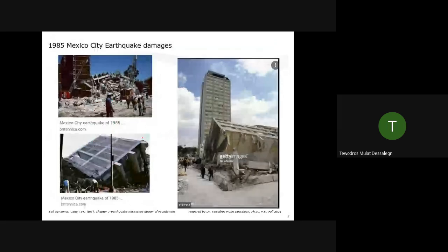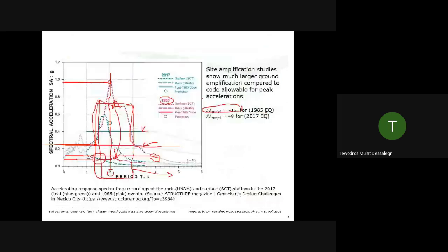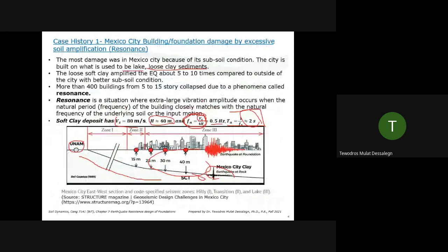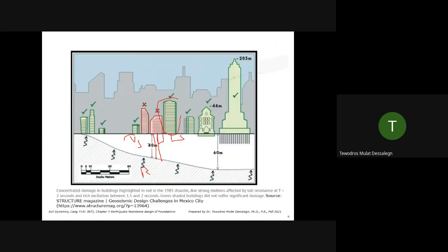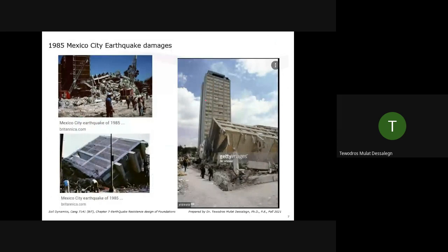So these are the damages in those buildings which were not designed properly. They were completely overturned. And see the tall buildings, the high periods. See the high period, see what acceleration is acting. For the high periods, let's say around 4 seconds, see it's very low acceleration, about 0.25 g in the design range. So pretty much nothing happened. Maybe a few cracks, window cracks, things like that, but no collapse at all.